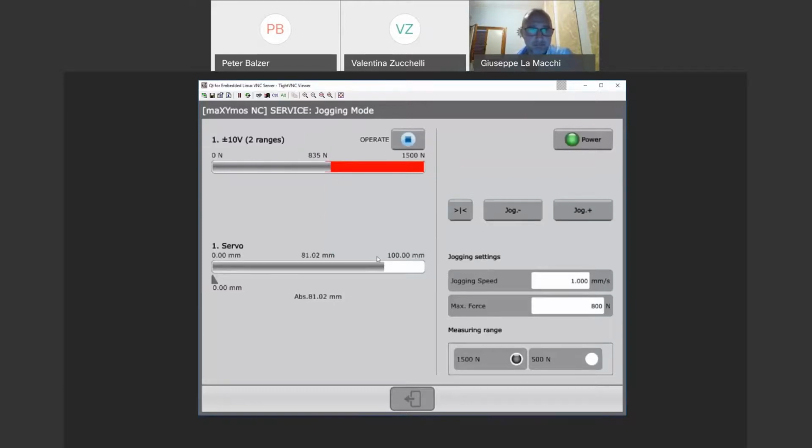So now, okay, we are on a hard mechanical block. Now we have about 81 millimeter. So now we know 75 millimeter is our idle stroke position, and 81 millimeter is the joining stroke position. So now we can go a little bit faster back. Then we can use these 2 values to set up our first easy sequence.